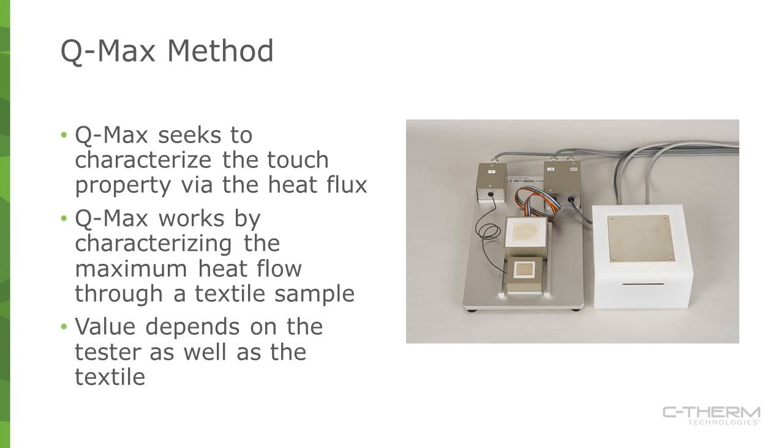And speaking to the points of difference between these methods, Qmax is used to characterize the touch property via the heat flux. It works by characterizing the maximum heat flow through a textile sample. It is approximating the same thermal property, that of effusivity. So you'll see the same units of measure represented in some of those test results. But it is done more as an approximation of the actual heat flux.